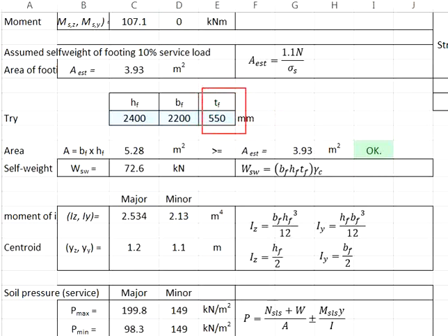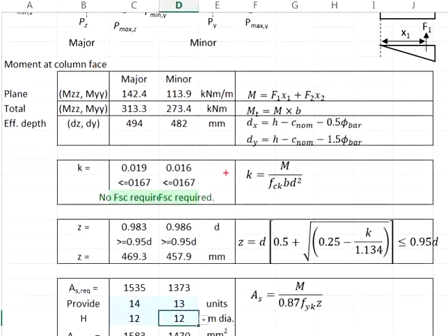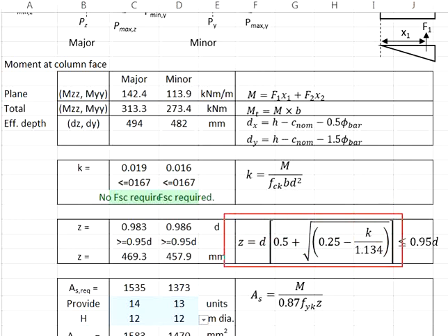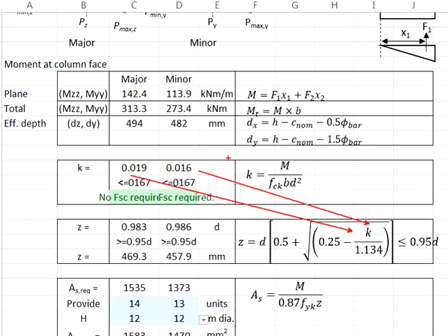Due to a relatively large thickness, this gives you a relatively large effective depth against the moment. If this happens, then normally you don't need any compression rebar. Now let us proceed. We need to determine the lever arm Z here. Use the K calculated in the major and the minor axis to determine the Z.